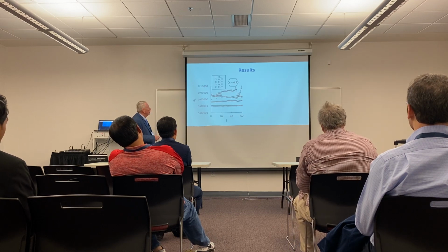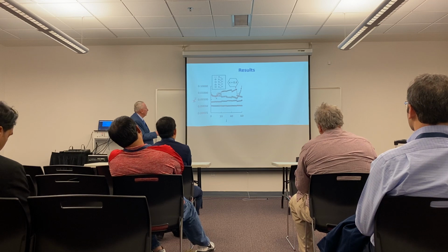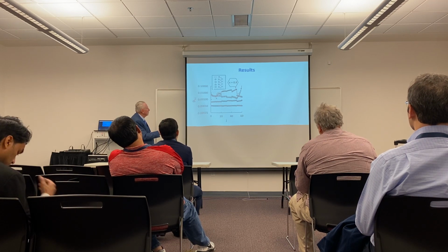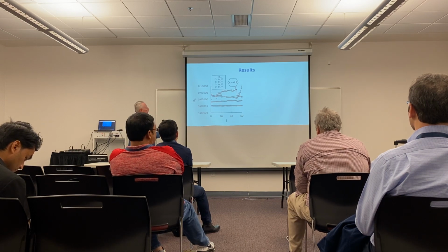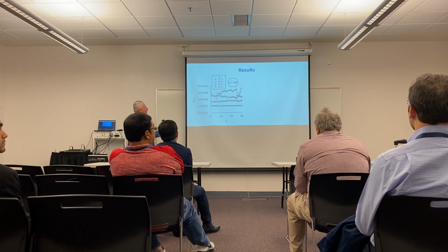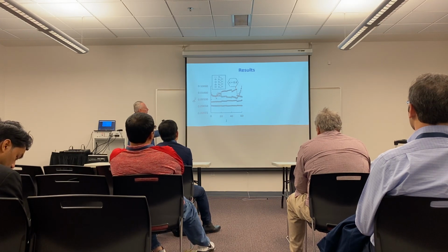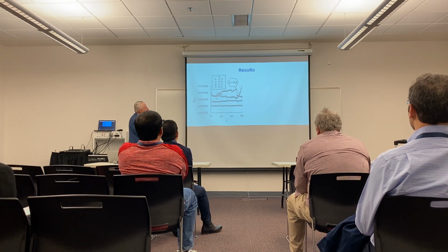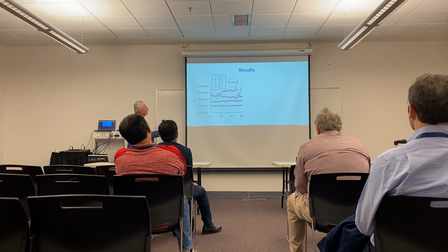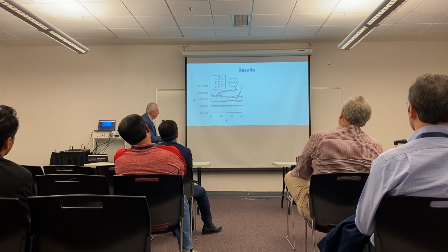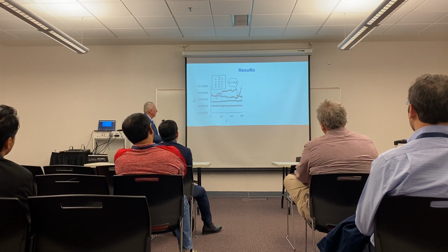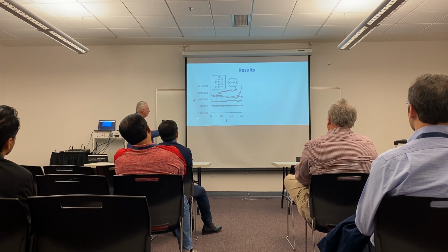Okay, so let's look at some results. In this case, notice the red number 1 in front of all these subscripts. This is from surface element 1, which is down here in this corner. Look, from the symmetry of this problem, it's 6 ways symmetrical. That number 1 could be right here, it could be right here, it could be right here, but I'm going to put it there. And so I'm going to calculate and estimate the distribution factors from that strip number 1 to all the other strips. So here's all the other strips, 1 through 60, and then here are the values of the distribution factors.